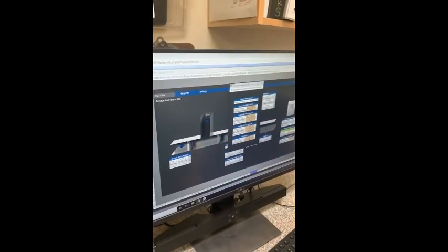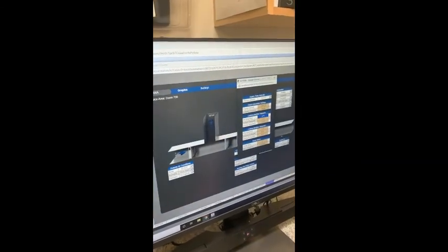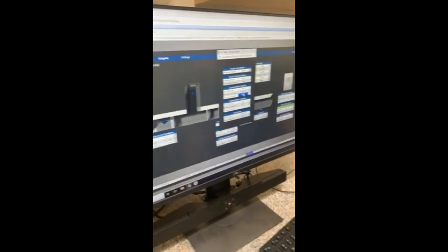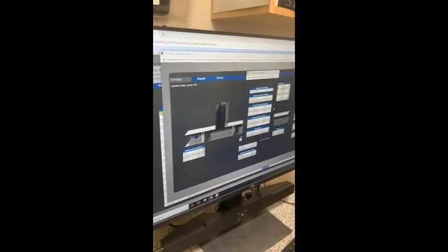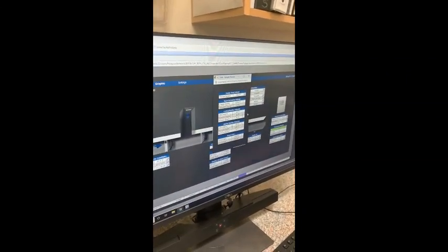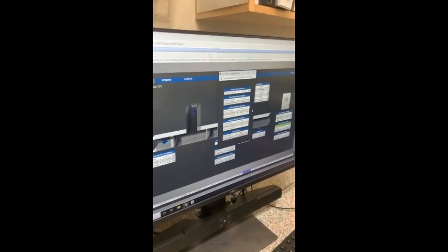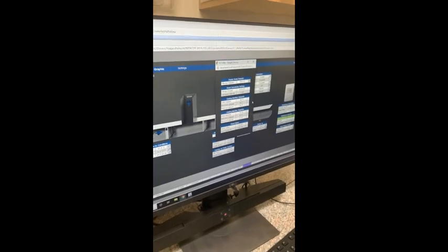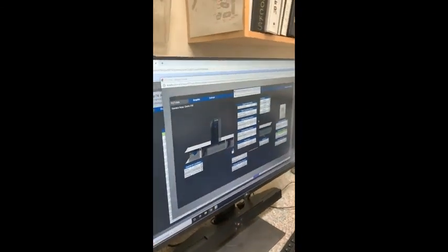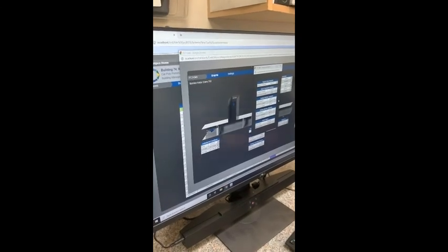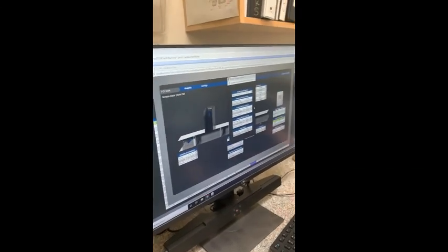Yeah, the initial set point is 65. Maximum is 65, and the minimum is 55. So it'll start there and then work its way down to 55. Okay. Just wondering, because the idea is once it starts needing cooling right away, it should need a huge, dramatic change, and then if that load increases, it should be able to decrease down.